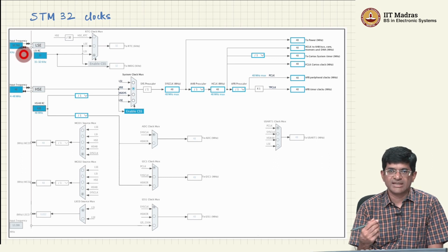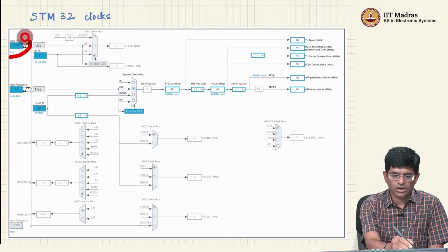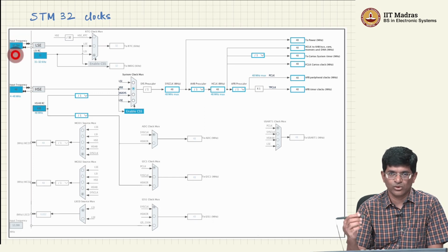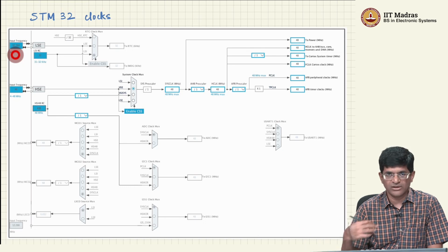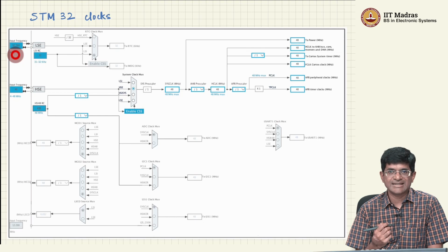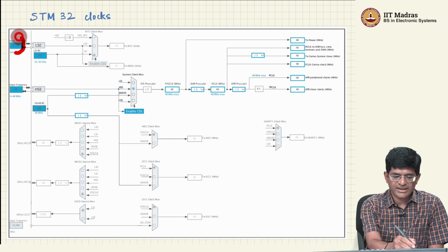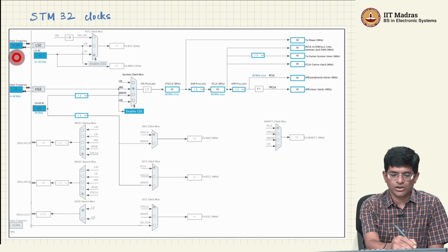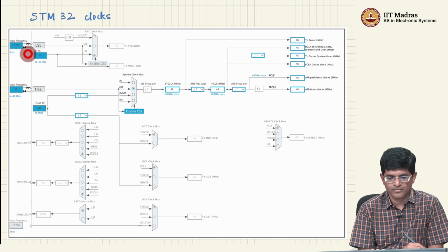Because 32,768 is exactly 2 to the power of 15, which means that by doing clock division from this 32,768, by counting for 16,384 and then again inverting every 16,384 clock cycles, I will get an exact 1 hertz or 1 cycle per second tick out of this. So that's why crystals running at exactly this speed are common and can be used in order to provide the real-time clock of a system.